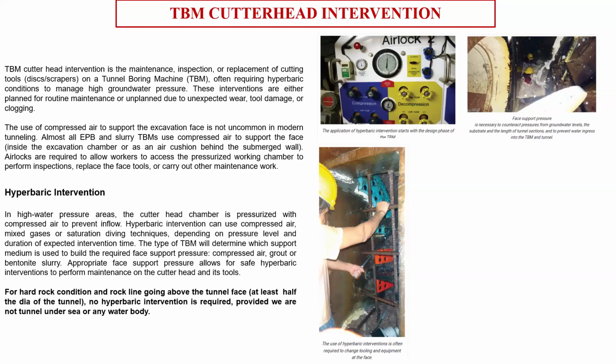Got it, sir. But nowadays there is the active articulation system. We are trying to manage all the curves, but it is not perfect. As I told you earlier, the TBM itself is a 20-meter length machine, so it's not possible, like power steering, to just rotate the car. And there might be one side where you have very limited space, because it has to move perfectly. The 20-meter machine has to be moved perfectly in a very tight curve. It is very difficult. You can understand the scenario.